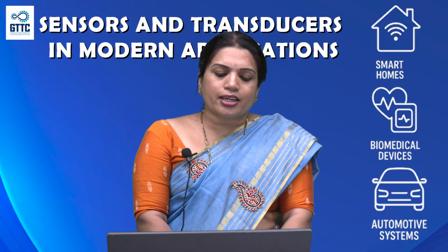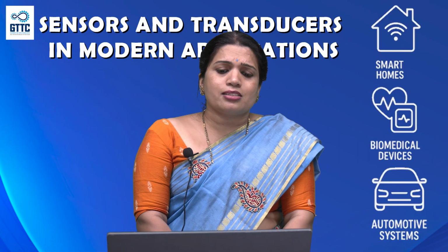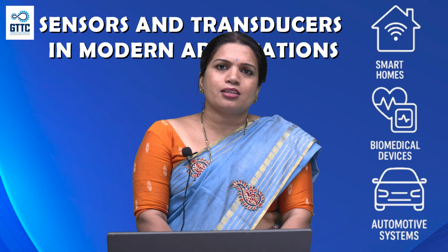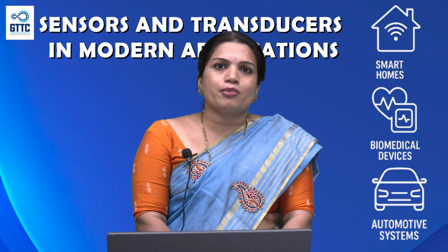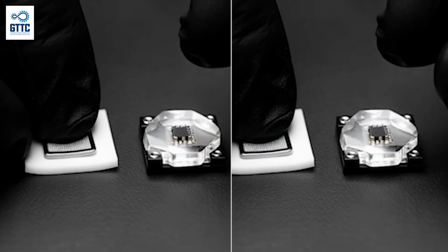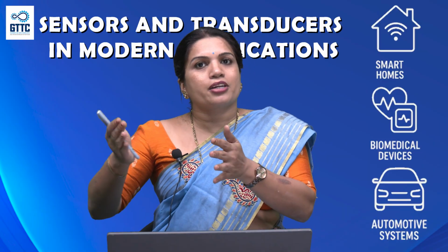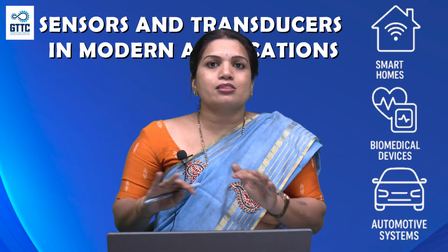As a conclusion, what is the difference between where we use strain gauge sensors and where we use piezoelectric sensors? Strain gauge sensors are used for static force, where the force is fixed. They are used for detecting weight, force and load. These are all static forces.